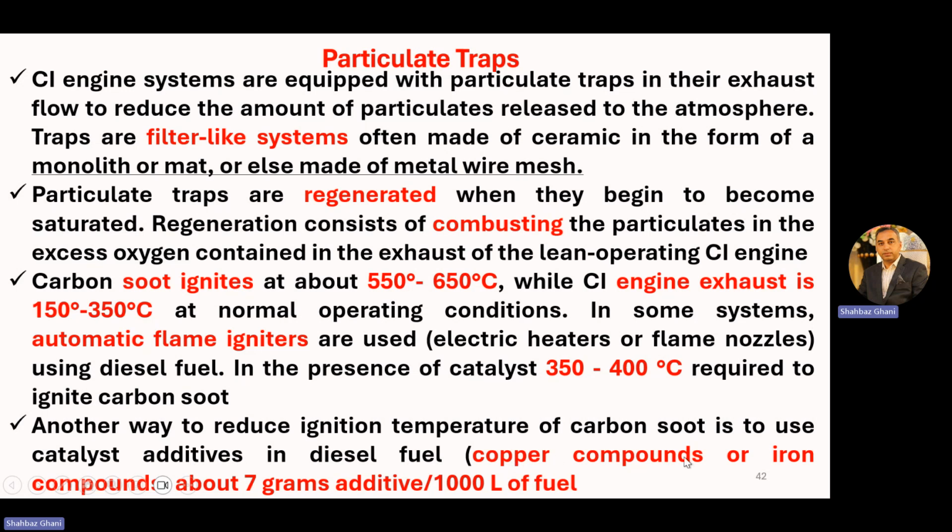Those are copper compounds or iron compounds, about 7 grams of additive per 1000 liters of fuel, to lower the temperature needed to ignite the carbon soot.